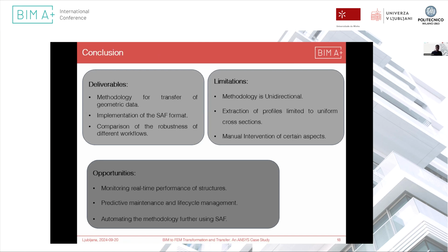The limitations were that the transfer of the model from BIM to ANSYS is still unidirectional, and there isn't any method developed to transfer the model back to the BIM environment. Also, extraction of the profiles was limited to BIM elements having a uniform cross-section, and there was manual intervention on certain aspects.